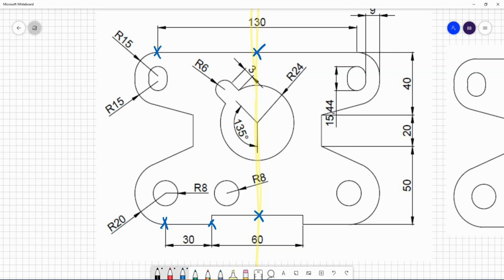Areas which I commonly do not know, which I'm going to mark as a red X, are areas such as here, here, here, and here. So these lines are actually using what we call a tan or a tangent line. We can actually only take these points from these green dots. Therefore, we can only physically make these components if we trim away the rest of our circle. So what I'm going to do is I'm going to show you how to basically set up, and then we're going to get going with this drawing. I'm going to break it down piece by piece.